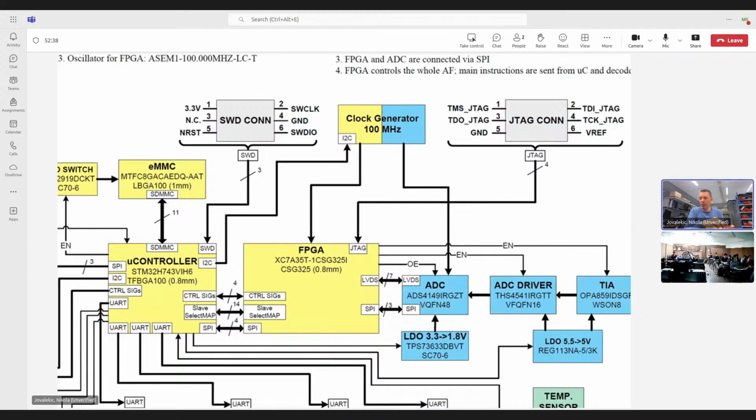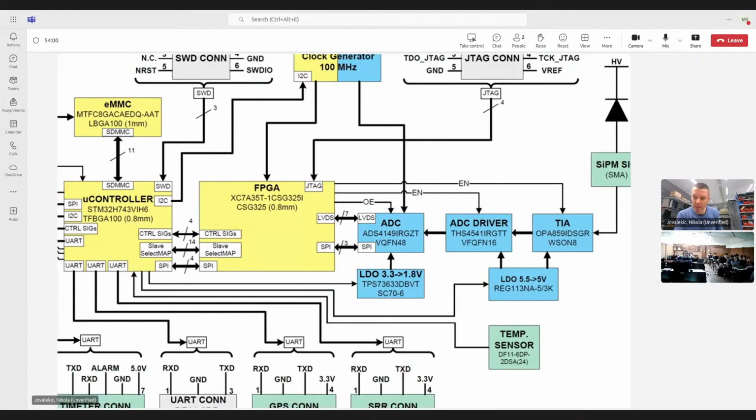In the same PCB, we have a lot of different kinds of signals, and then an approach that can be used is the clock generator waves or signals can be connected to the devices, such as FPGA, microcontroller, through microstrip lines or different kinds of waveguides in the PCB, because we can concentrate the electrical field there and then put the control into the rest of the PCB. I understand your point.